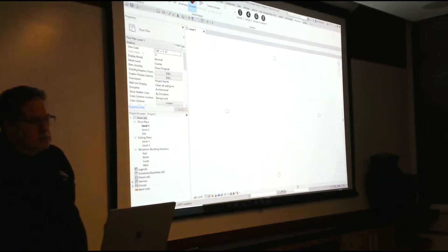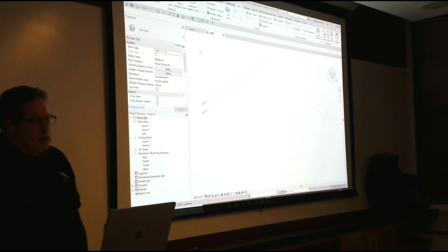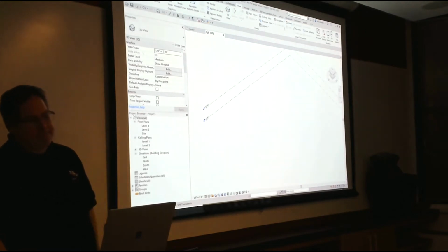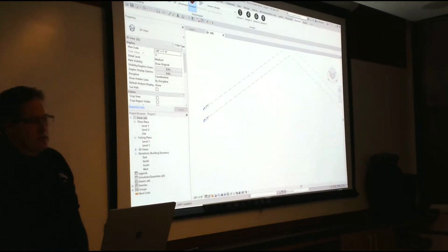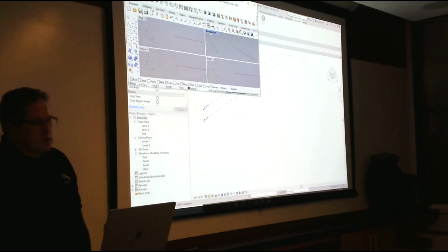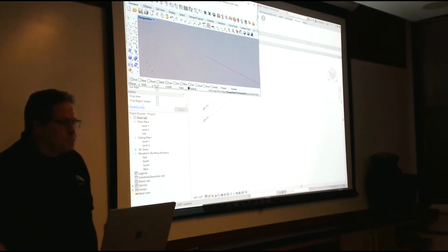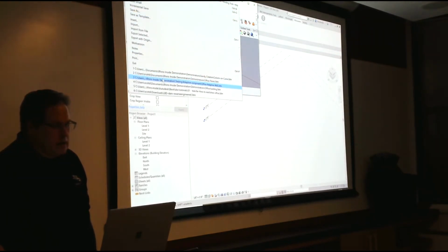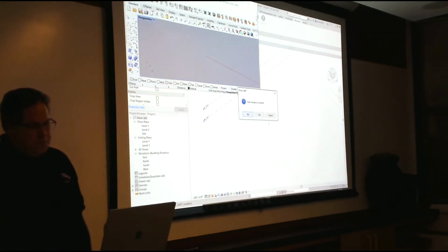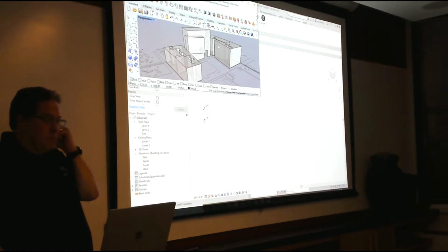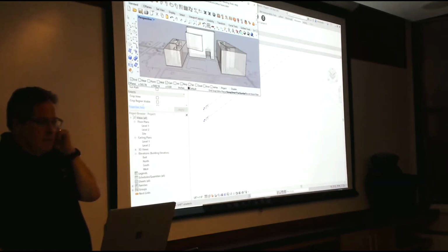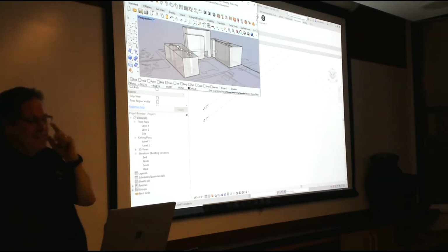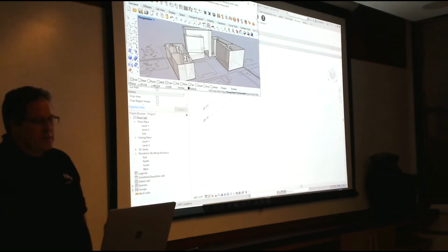I hope we're going to go over 5 different workflows here. The first one's going to be the classic one: how do I get my Rhino stuff into Revit? So we'll start over here. When I press that button, once Rhino's loaded, you can see I get a new toolbar in Revit called Rhinoceros, and I can click on it and start Rhino running inside Revit. Let's just open a model. This looks like Rhino because it actually is, and it just happens to be running in Revit. So you can move around a standard Rhino model every day.